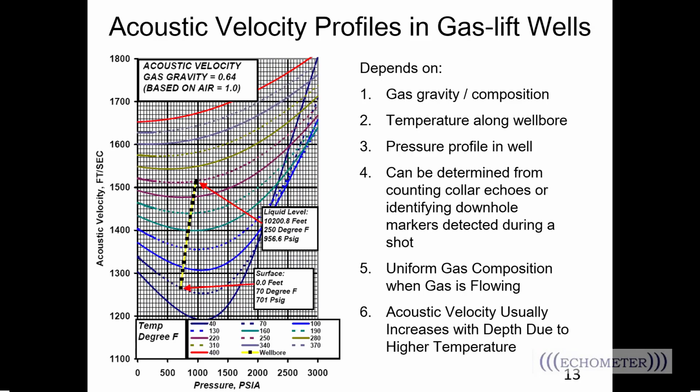That's right. And so the main thing he said to do was that you find a well that's not working and producing as it should be, and the operator alerts him, and the operator first goes to the well and drives the liquid in the tubing down the tubing. It doesn't change the casing conditions at all. And then he starts shooting down the dual shot when he gets there, once liquid level is down past the operating valve. So the pressure in the casing is a lot higher than the pressure in the tubing, and I was surprised it would work, but it doesn't seem to matter.